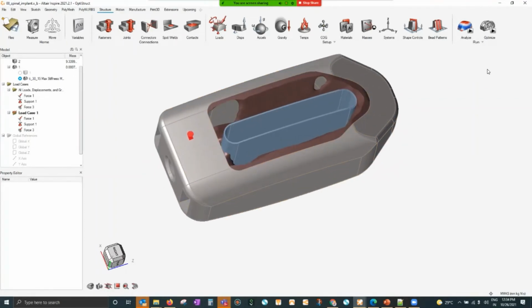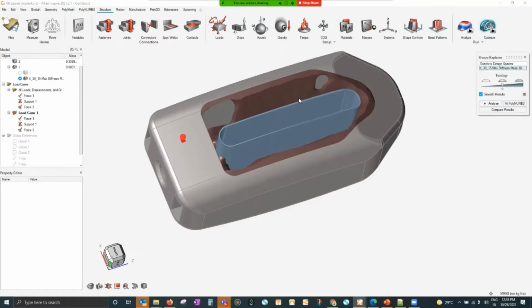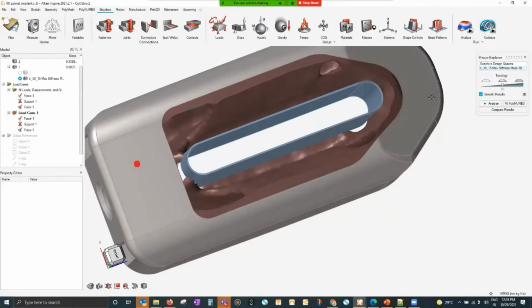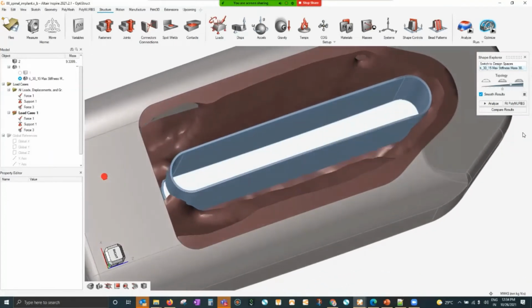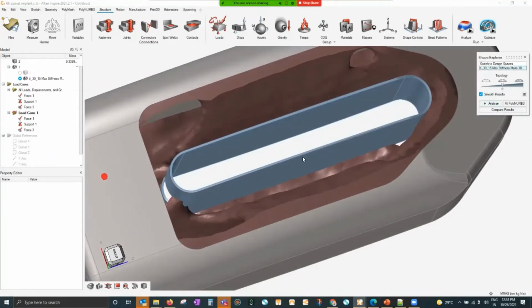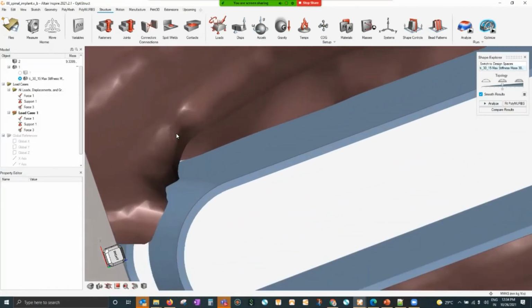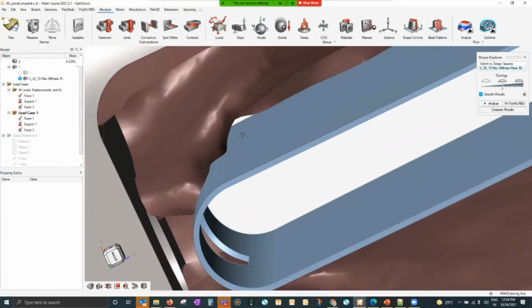All you have to do is go to this shape, show optimized result icon. So this option, go over here and it will bring this slider. First thing we'll do is put this slider a little bit, two steps, to the right-hand side. What it will do is add some more material. Why am I adding some more material? Because if you see, in some of the areas these connections are not very proper with the 30% target.